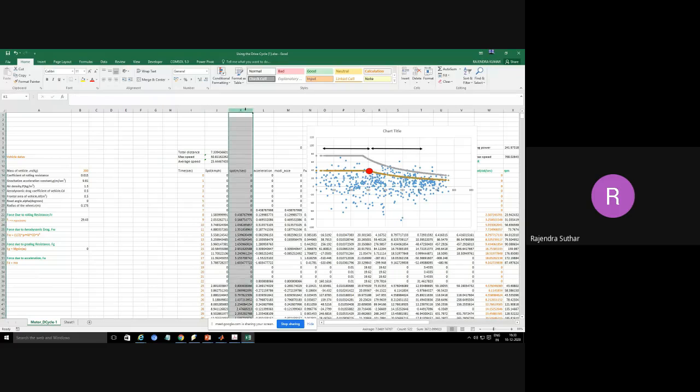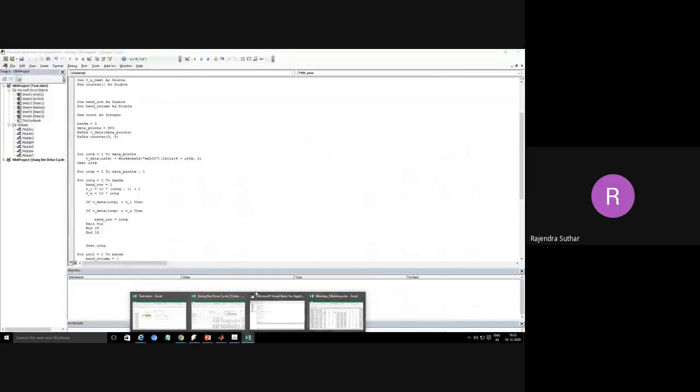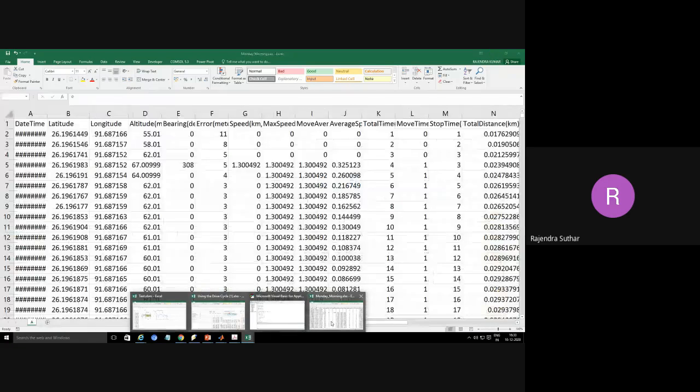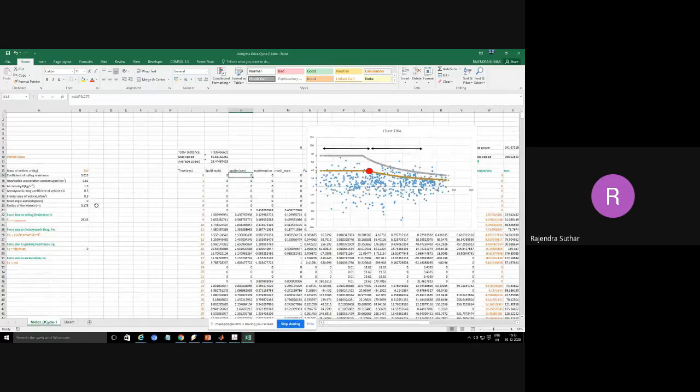So we can make one column here, and in that column we can put this altitude data. From that altitude data, differential altitude data, we can find the road angle. The same data can be added as another term, extracted from the GPS. That thing is not implemented here because the route was completely flat. Only these flyovers were there.